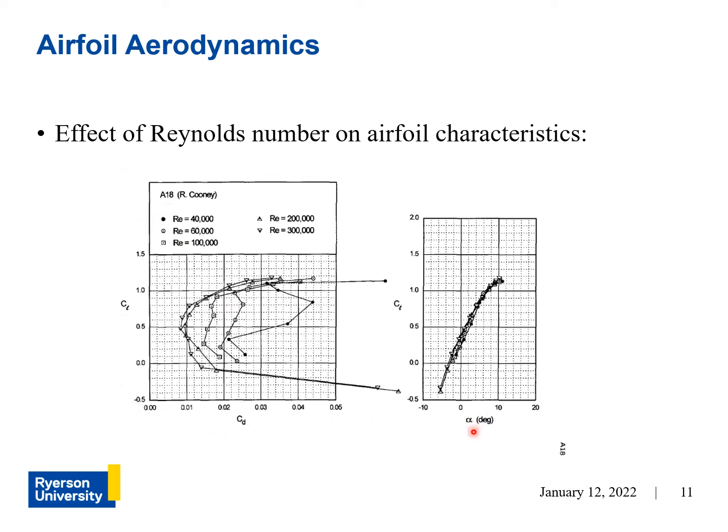On the other hand, at least at these values of Reynolds number, the lift isn't as drastically affected as the drag. So the Reynolds number is important to know because of how the airfoil drag characteristics will be affected.